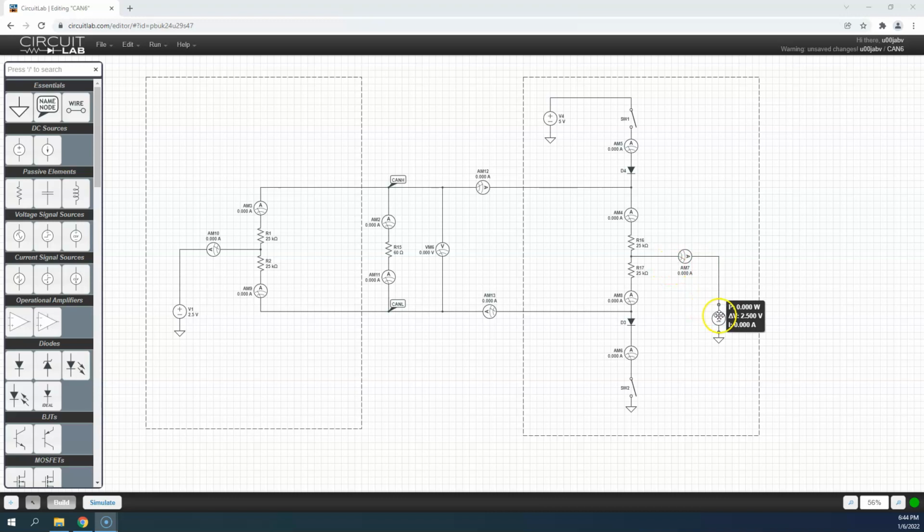It's like, well, I've got 2.5 volts here, but I have 0 volts dropped across the terminating resistor, because both CAN high and CAN low are held at 2.5 volts. They have to be, because it's in parallel, right? So if I looked at this with respect to ground, there's nothing here that's grounded. This is grounded, this is grounded, this ground is open. There's no current flowing because there's no path anywhere for anything to get back to ground.